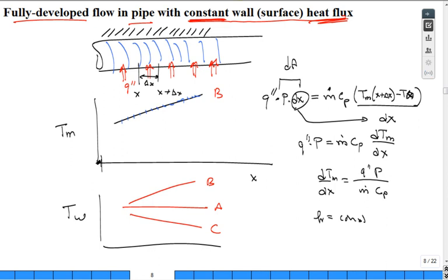All right, we stop. Okay, some people are correct, that's for sure. But we use this equation that Q double prime is equal to h times T of the wall minus T mean at that location. Or sometimes I should have written this as T_s, put an S here instead of a W. It's the surface or wall temperature.